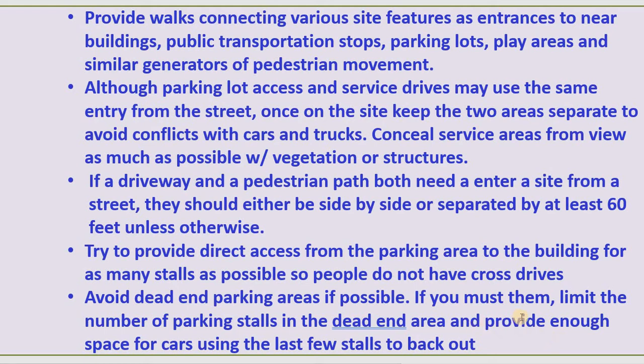If you have one, limit the number of parking stalls in the dead end area, and provide enough space for the cars using the last few stalls to back out. If it is a dead end, that means you cannot drive further, so we need to design fewer parking stalls and provide enough space for the car to back out.